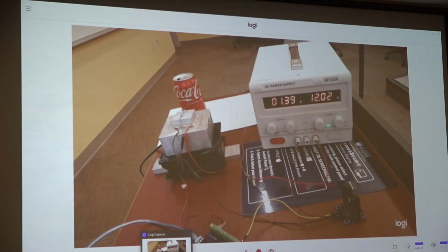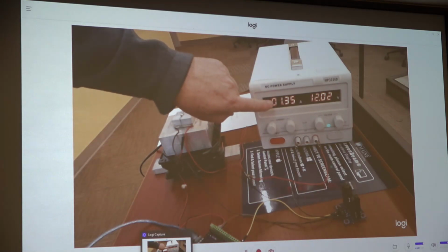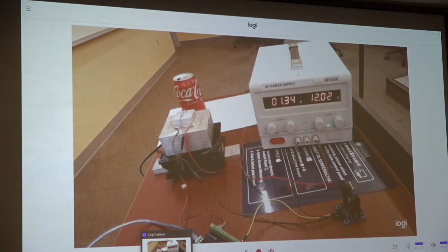So my power that's being applied is proportional to the error with the set point. The closer I get to set point, the less and less power this thing's applying. And you can see that right in the amperage. The voltage is give or take constant, but that amps is going to keep going down, down, down.